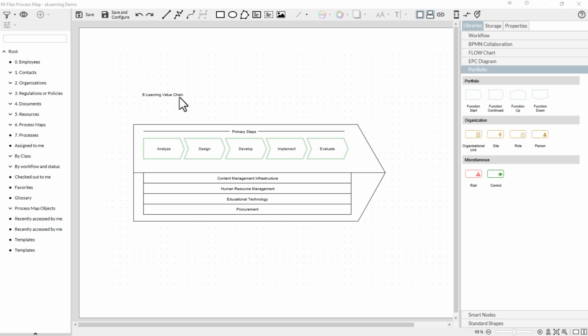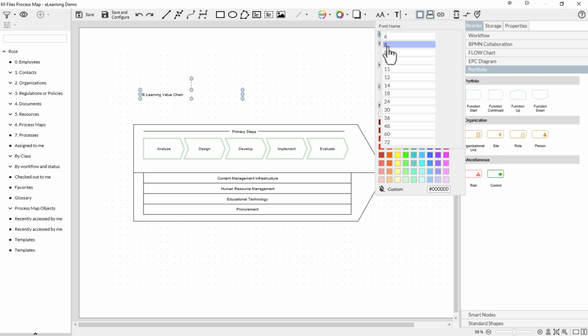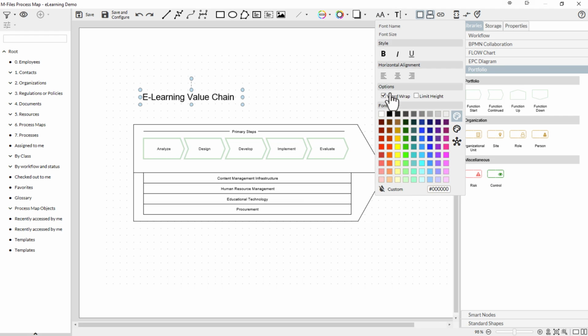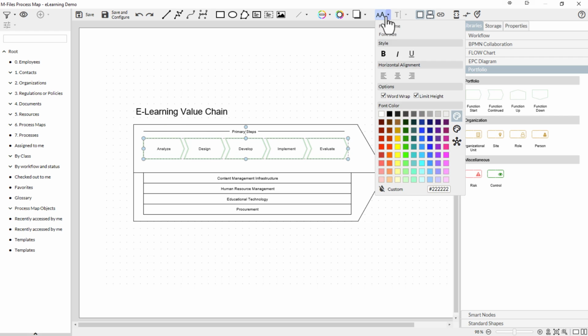In the toolbar you can access the drop-down menus Font Format or Label Format to change the position, color, font size, and type of your text and label. Please make sure that you select the right text element prior to assigning the formatting. You can select multiple text objects using the rubber band or shift-click selection and change their font format simultaneously.